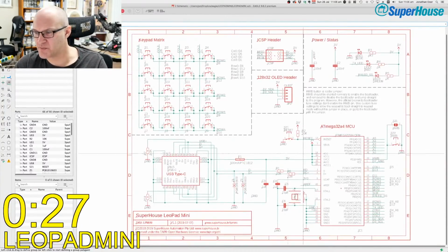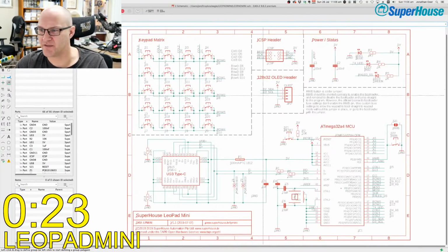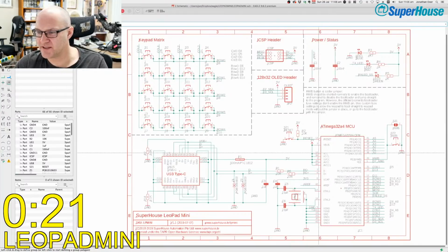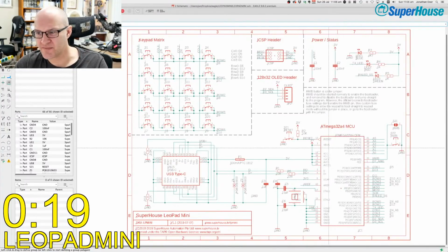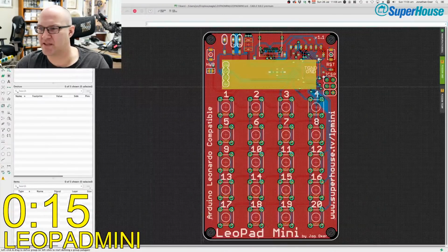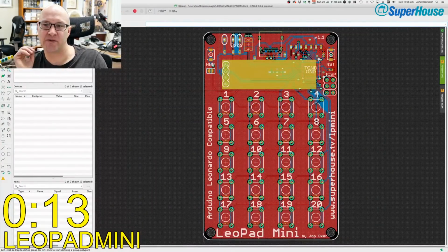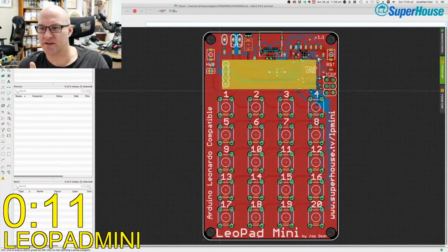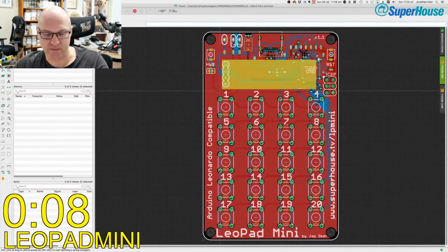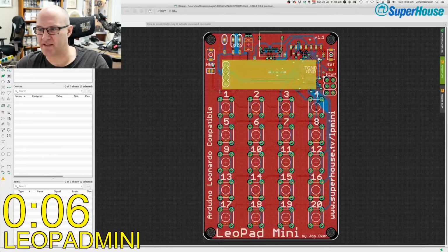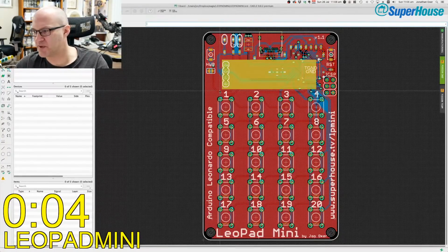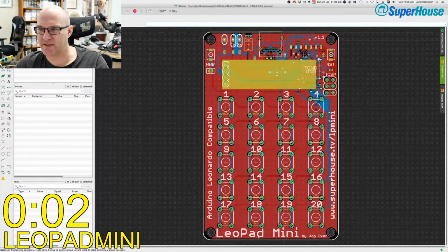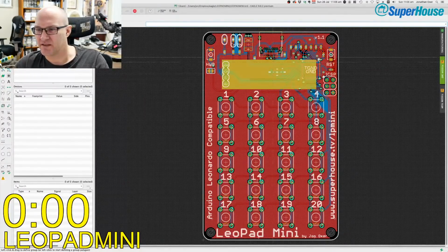So there's a USB-C interface, there is a header up here for an ICS, oh, it's not ICS, over here, OLED. It's got the little OLED, so when you press a button, the ATmega can do something. It could send a keypad event, it could send a mouse event, or whatever. I'm using it to send macros that go into Eagle. So I can do things like, well, what I'm doing right now, switching between the schematic and the PCB view. I'm doing that by pressing one button and running that. That is changing layer visibility.